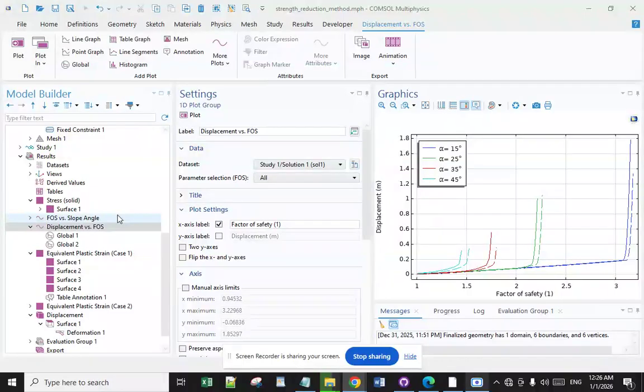The limit equilibrium approach necessitates the consideration of the sliding body as a rigid solid and the assumption or prior knowledge of the location and shape of the sliding surface. Determining the precise position of the sliding surface of a landslide is challenging in practical application.